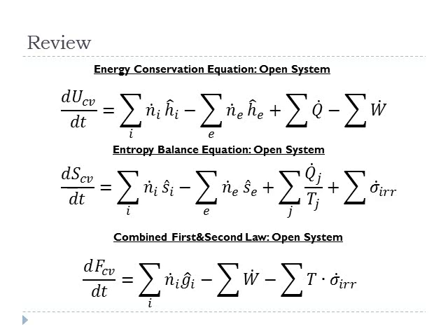The entropy balance equation is that the change in the entropy inside of that control volume as a function of time is equal to the entropy that enters or exits in flow of material. So we've got flow times a molar entropy associated with each flow.